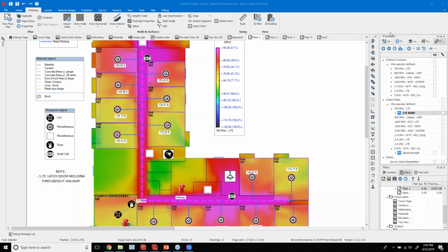So when you design your network, SCs are going to be typical. You could go with a small form factor to reduce size of housing, so that might be an LC style connector. But I would ensure that you've got an option to do a field installable version of that connector if needed.